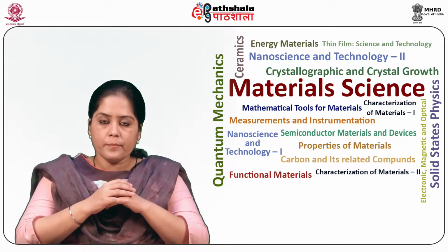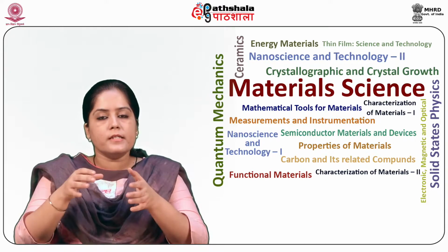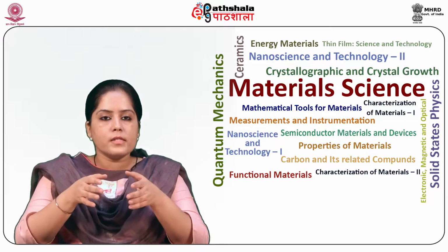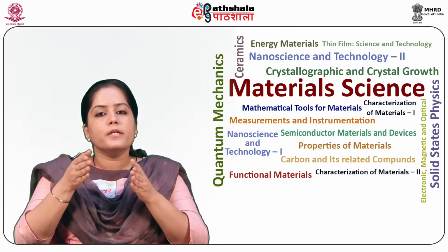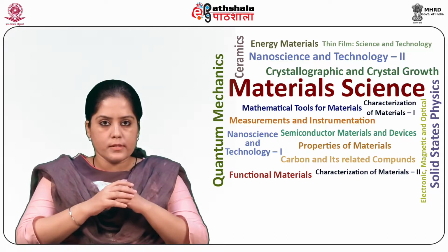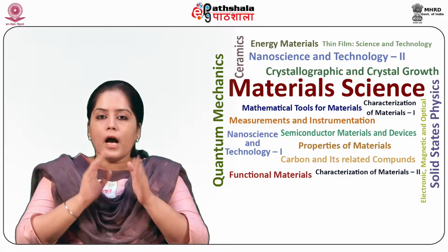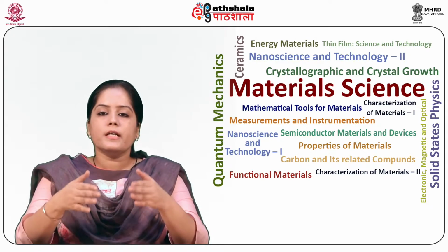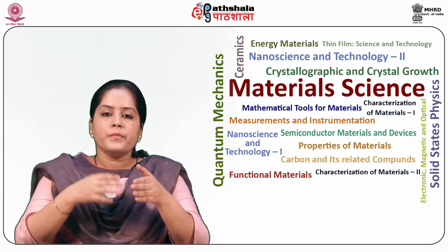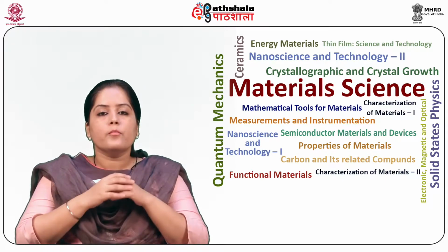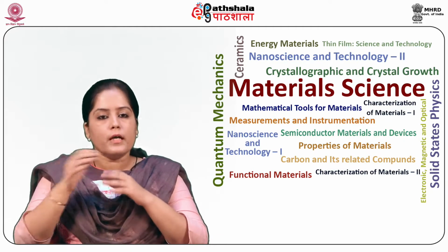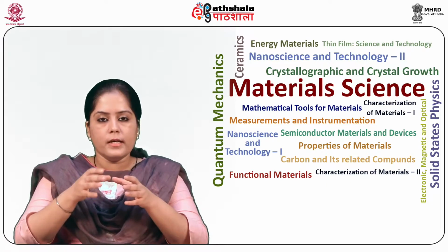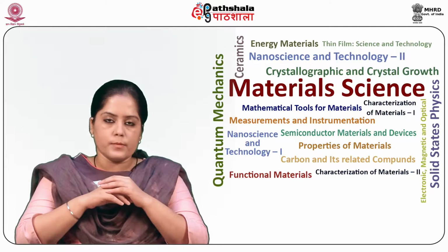Self-biasing of the target. The target automatically tends to bias itself more negatively than the anode as a consequence of the difference in the mobility of ions and electrons. The reason is that the high mobility of electrons enables a larger electron flow through the anode, while the less mobile ions provide a lower current to the cathode. Due to this asymmetry, a negative biased current is created through the plasma.